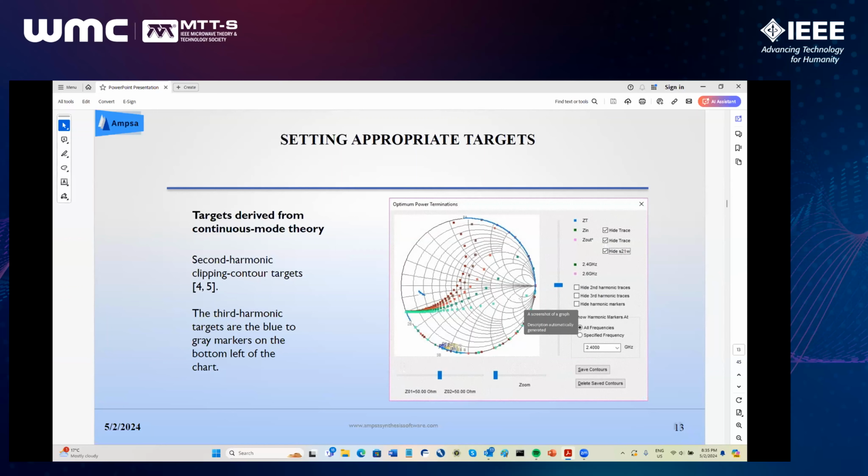What do you mean by good performance? The power will be the same, but the efficiency will not, because if you pick this as a second harmonic, it's lossy. And on that lossy line, there will be losses in the second harmonic termination. So basically, the efficiency is not constant, while the power is constant. So you have to have a lossless termination, so as not to have power in the second harmonic.